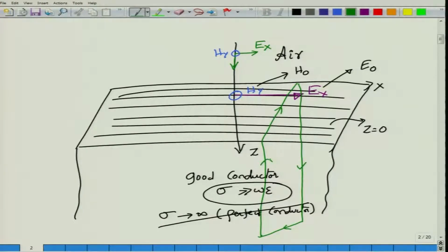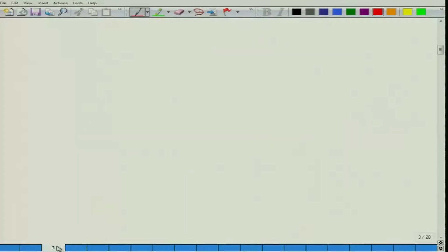Okay. We call this loop, let us say we name this loop A B C D A. The J vectors are all coming out perpendicular to this loop, because the J vectors are all along the x axis, and while these are the J vectors that come out on the surface, they are uniform, but as you keep going inside the conducting material you will see that the amplitude starts to decay exponentially. So the amplitude is decaying exponentially. So what is the total current enclosed?